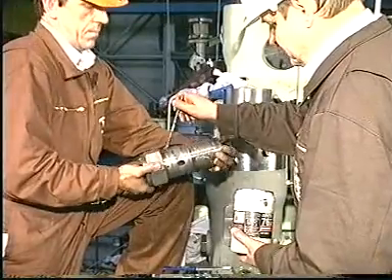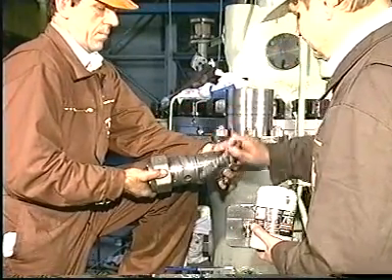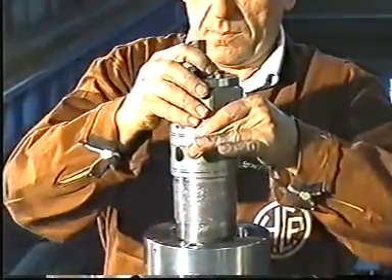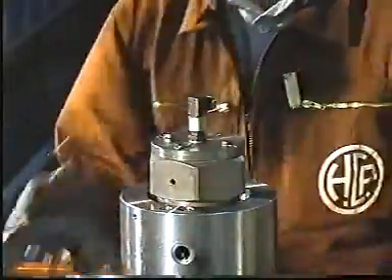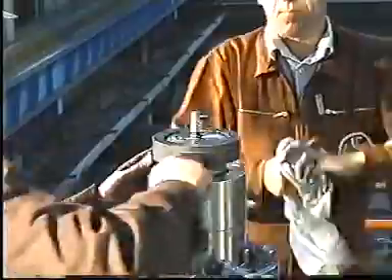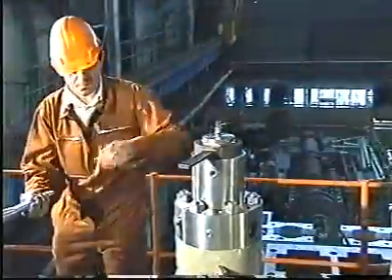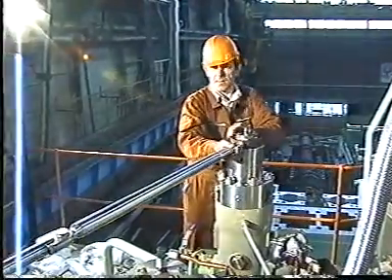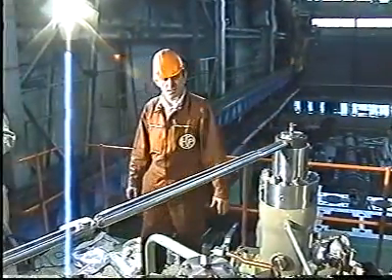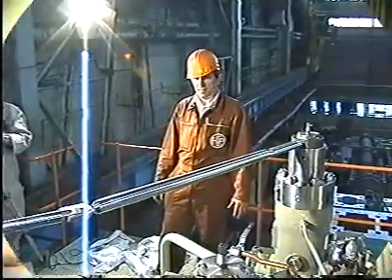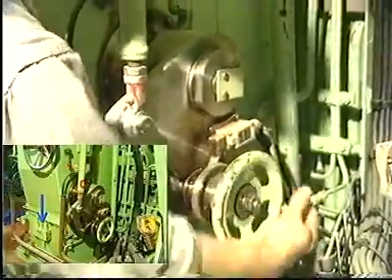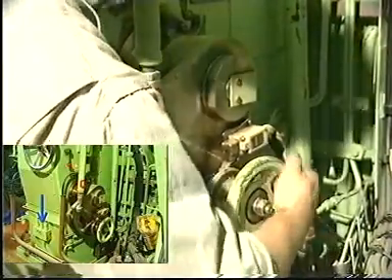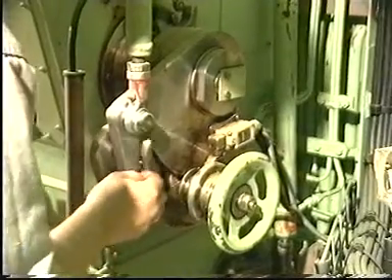Provide the puncture valve with new sealing rings and lubricate with molybdenum disulfide. Tighten the puncture valve to the torque stated in the instruction book, Volume 2, Chapter 909, and mount the plug screws, cover and control air pipe. Finally, change over to normal engine control. Make sure that the VIT-system changeover valve is properly connected.